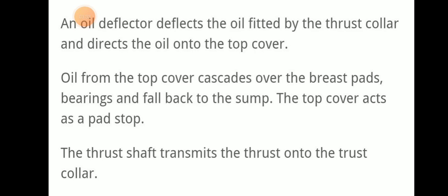The oil deflector, as the name suggests, deflects the oil flung by the thrust collar and directs it onto the top cover. Oil from the top cover cascades over the thrust pads and bearings and falls back to the sump. The top cover acts as a pad stop.